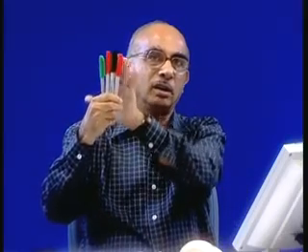If I collect, for example, 20 bottles, the first 5 or 6 might be produced with one speed of filling. The later ones might be with some slightly different speed of filling, because hydraulic pressure changes, something else changes, some controls change, and so on and so forth. So in fact, it turns out that one of the requirements we have in statistical process control is when I draw a sample from production, these should reflect one condition of production. That means they should be alike.